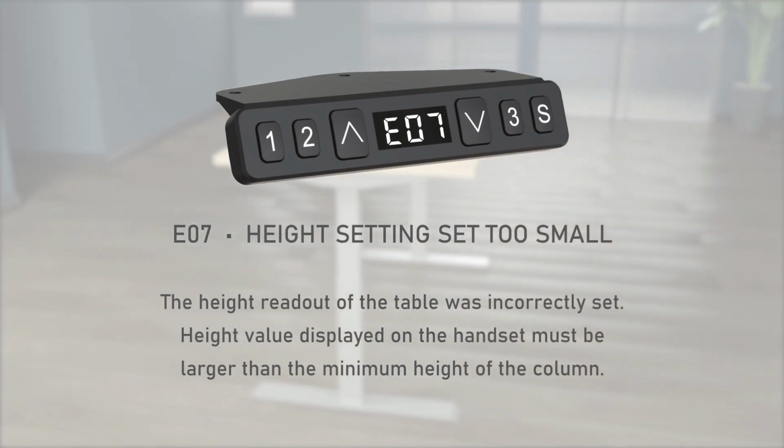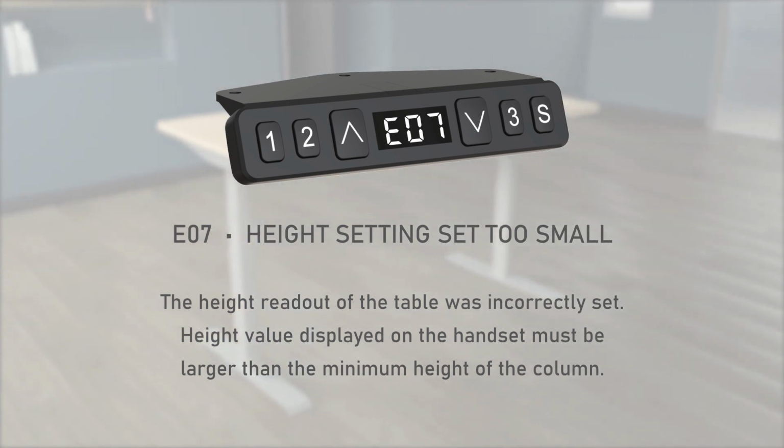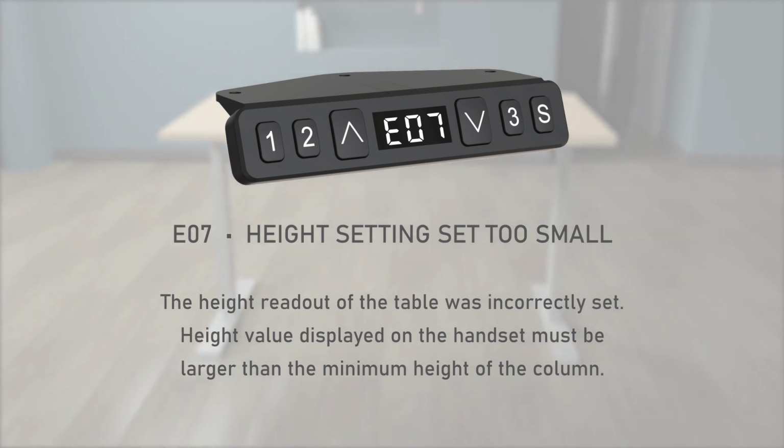E07, height setting set too small. The height readout of the table was incorrectly set. Height value displayed on the handset must be larger than the minimum height of the column.